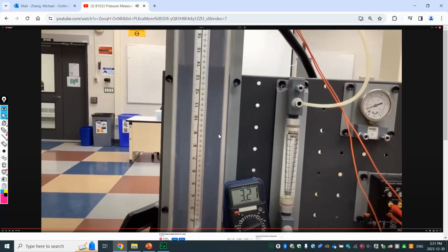The purpose of this lab is that we want to convert this physical quantity, the water level at different heights, into an electrical signal. For the electrical signals from lab 1 to lab 10, we use what we call discrete, logic, or digital input and output. It's only 0 or 1, low voltage or high voltage. We don't care about any voltage in the middle. But for this lab, it's different.